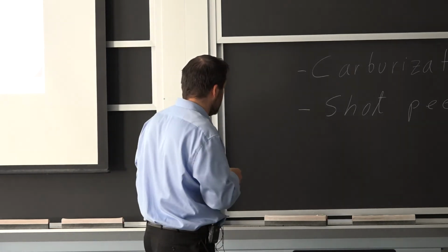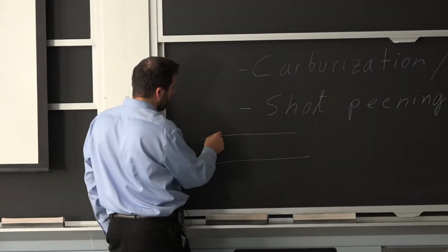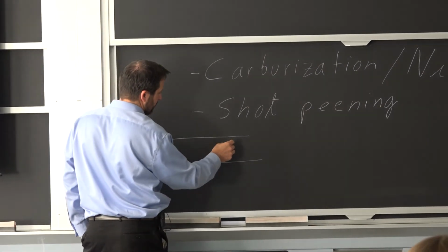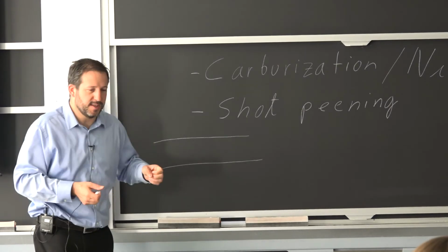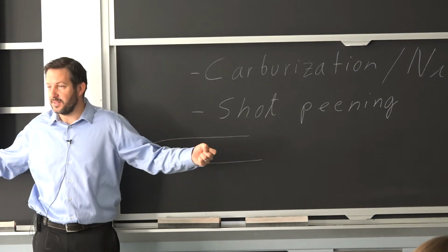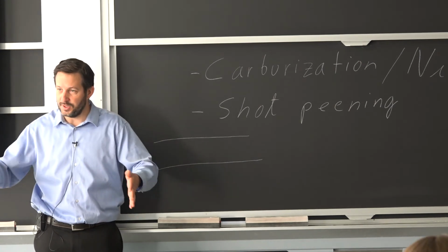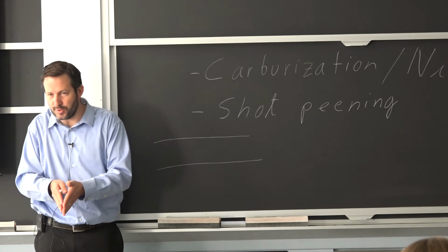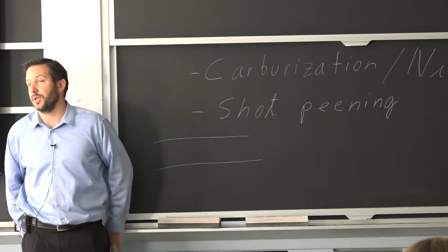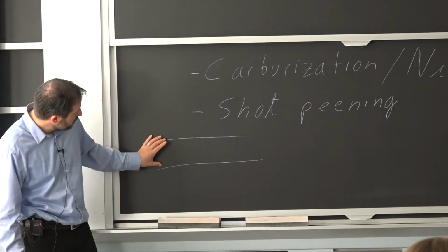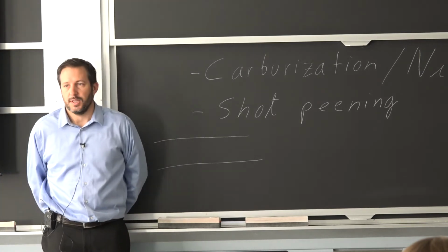So why is that? Let's say I have the surface here, and I come and compress the surface. I'm forcing this surface to become a little narrower in thickness. What that means is the surface is trying to expand sideways. It's getting squished and it's trying to expand, but it is constrained. Each little ball, when it hits, can't really grow the plate. So the plate stays the same size and the surface just becomes in compression. There's a net small reduction in thickness, and there's this compressive stress field in plane.